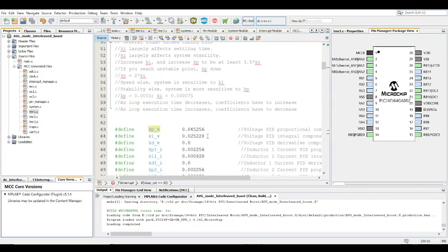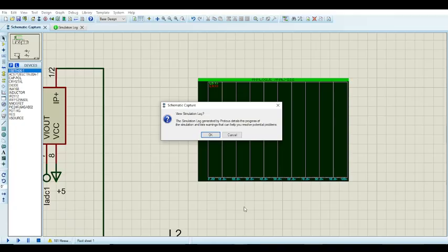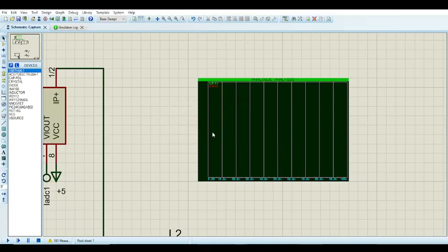Let's see here, yeah, so this is the kp and ki values. Obviously I've gotten creative with it and raised them quite high, but always start with this. It will be quite slow when you try it out, but at least you have a starting point. Okay, I can make it faster following these rules here, making sure that kp is at least 3.5 times greater than ki, and should be good. I think it's done. Then just say okay. And you see the readings.